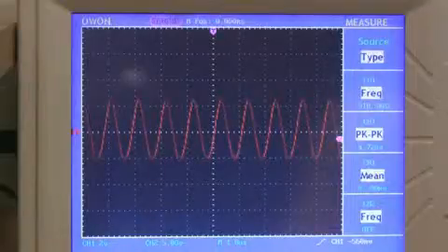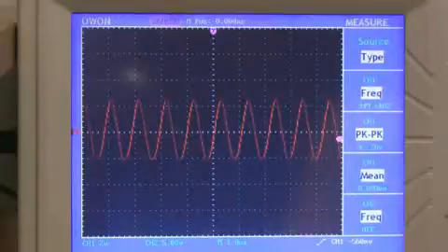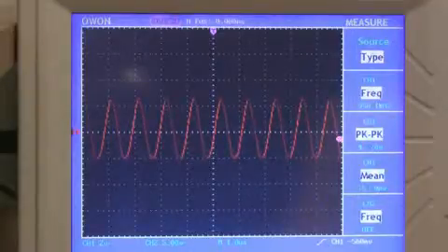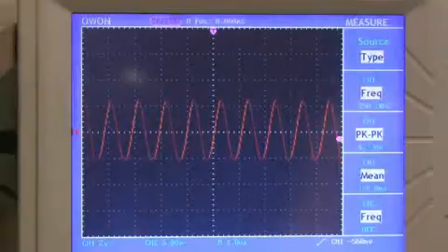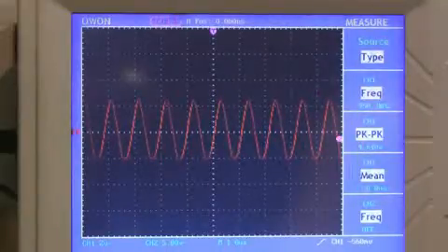AM is amplitude modulation, and I should probably explain what modulation is. You know how we started out by transmitting a wave of 950 kHz and the receiver detected it? That wave is called the carrier wave, and it's typically of a high frequency, anywhere from 100 kHz to 10 GHz and beyond. That carrier wave, on its own, isn't really useful for any kind of data transmission. All we got was constant radio silence.